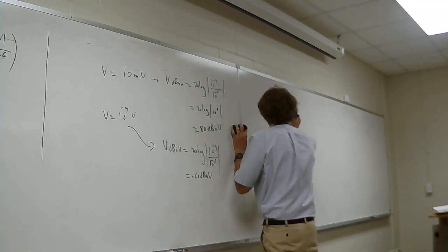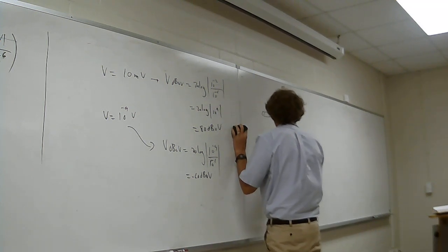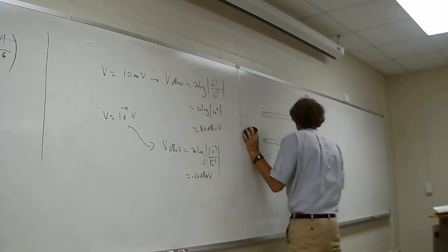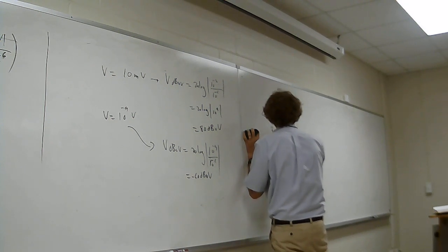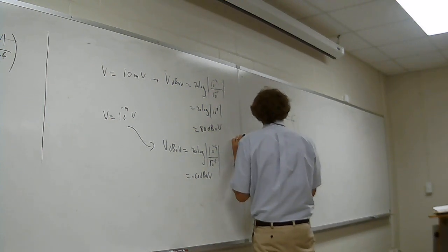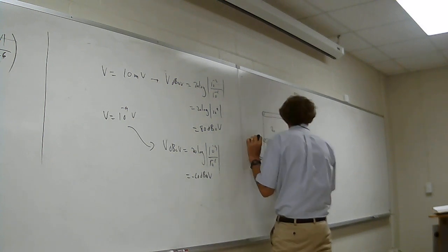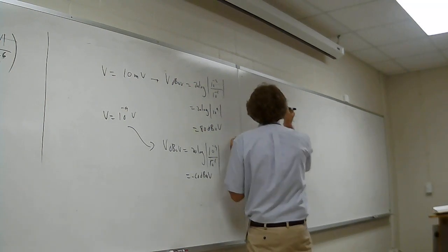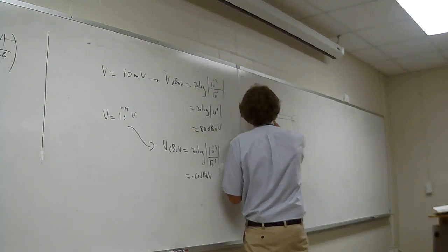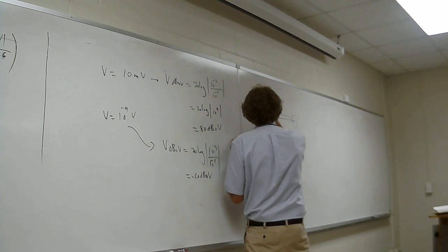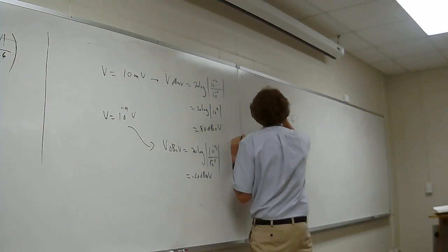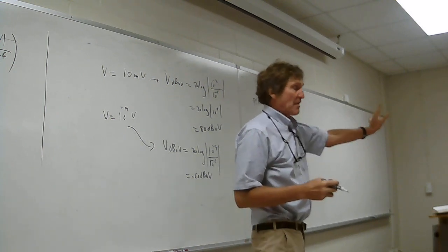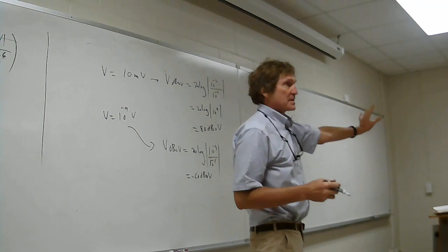So if I have a transmission line as such, and we can assume this goes on forever and ever, and it's got a characteristic impedance of Z naught. And this is going to be Z equals 0 right here, and the power is transmitted this way. So that's the direction of power flow. I come over here and I'm going to say that the actual power coming down this line, P of Z, its average power, is going to be some P0 e to the minus 2 alpha Z. Now y'all follow me? That's just standard.